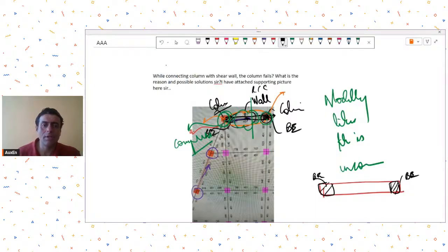Now what might be happening in your model is that because you have modeled them as line element columns, the moments being taken are high because they are at the ends of the shear wall. So there is a large concentration of in-plane moment, and that might be getting converted to a compression-tension couple in the column. For that compression, ETABS will start designing these columns like a normal line member, like a normal column. So it will consider additional effects of slenderness and of minimum eccentricity, etc.